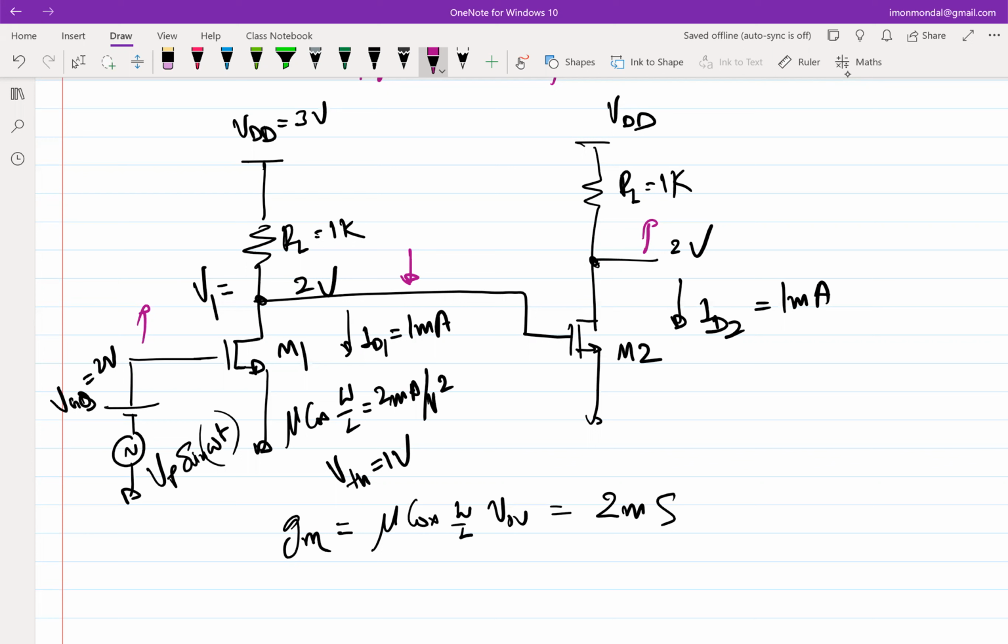Yeah, right. VGS is increasing. But when VGS is less than the threshold, that time it will go to cutoff. If it starts off in saturation and is going away from saturation, I mean, going deeper into saturation, isn't it? So his question is, how do we figure out whether M2 is going towards cutoff or towards triode?